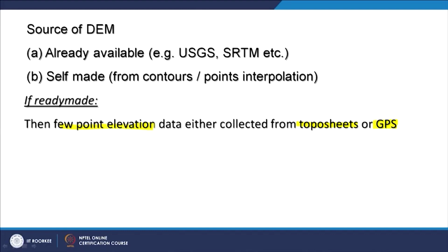But I know that in order to assess the quality of a digital elevation model generated using Cartosat, which is available at 30 meter resolution freely for India and which you can download from the Bhuvan portal, they have used those 30,000 ground control points. In that way, these test elevation points have been used to assess the quality.